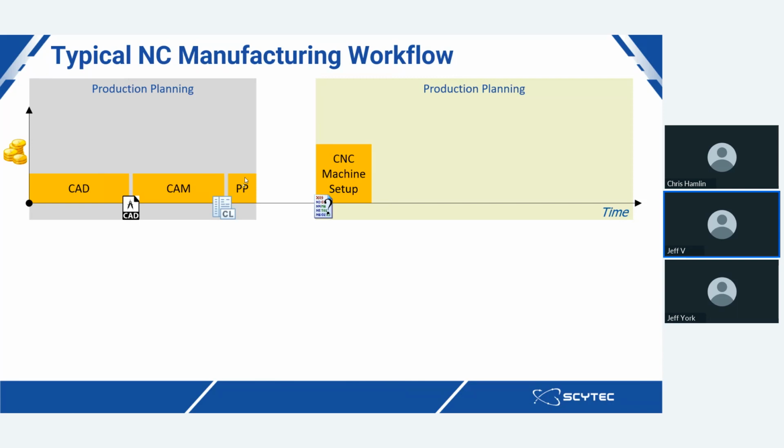And when you get your machine set up, when that part is finally ready to run through its first tool proof or first article, you have your various items that you need to add to your machine before you can hit cycle start. You've got your program, you've got your fixture, your casting or billet, whatever you're cutting from. You've got various offsets, you've got tools, maybe some subroutines or anything else like that. And then you go through typically a prove-out process. I would imagine this resonates as a very familiar workflow with many of you.